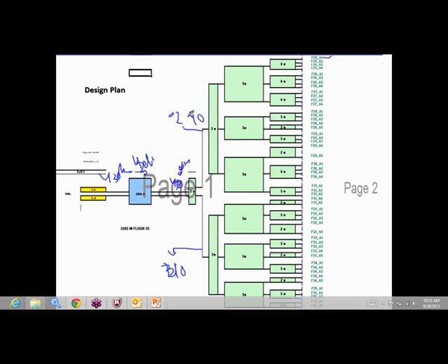This 40 watts becomes, sorry, not 30 watts, this 40 watts becomes 37 dBm over here. Okay, so this 37 over here, this is a three-way splitting. So three-way splitters have 4.5 dB loss. So let's assume it is 32.5 and then again 4.5 loss. So this is 27, sorry, 28 over here. So 28, then we have a four-way splitter, which means